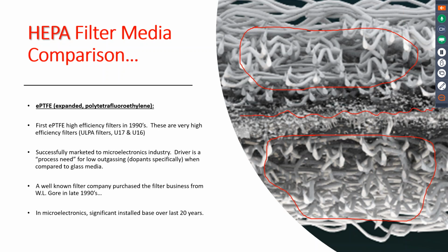So when you add your aerosol, let's say your PAO, polyalpha olefin, for example, it actually binds to the PTFE media. As the aerosol begins to bind to that membrane, as you can see, there's very little surface to allow a lot of that oil to bind. So in a very short amount of time, it begins to clog the media, because there's very little place for it to go. Right, and we can kind of see that in the particulate in the picture.